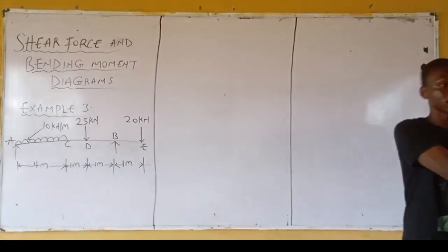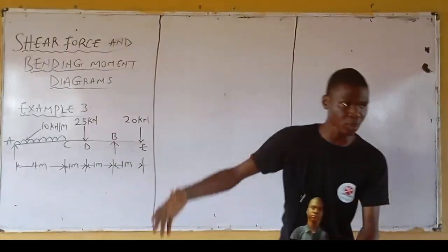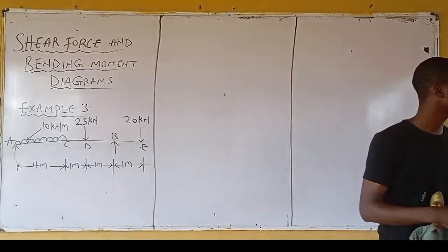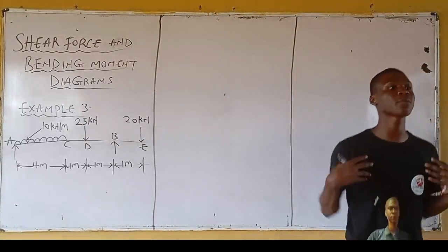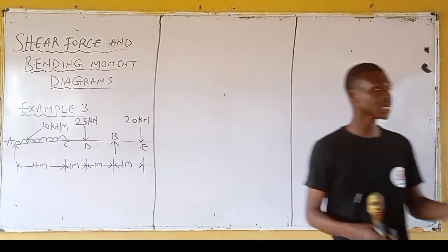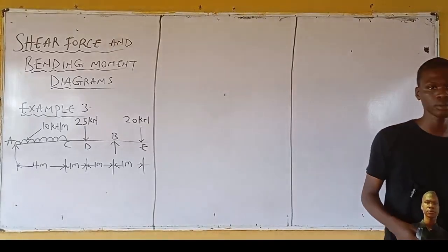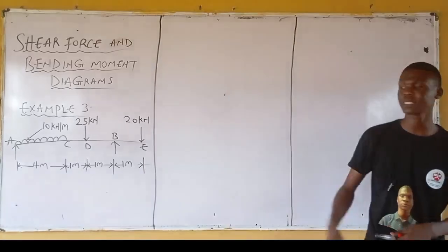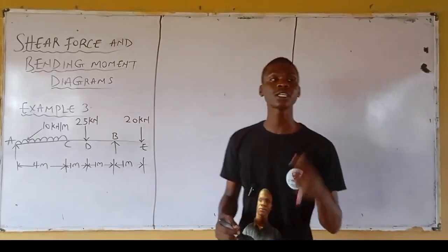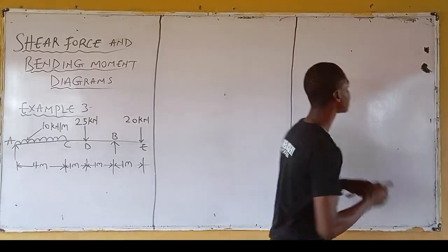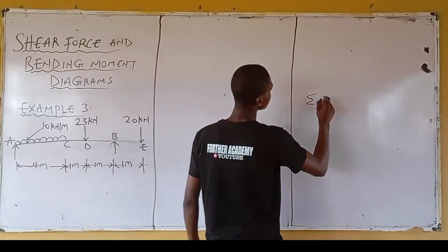If you say statically determinate, or you say overhanging beam, both are correct, right? But when I ask what type of beam is this, your answer should be an overhanging beam. Now for the last time, what type of beam is this? An overhanging beam, and it means equations of equilibrium are sufficient to analyze them. As far as this question is concerned, I'm making use of these 3 equations.